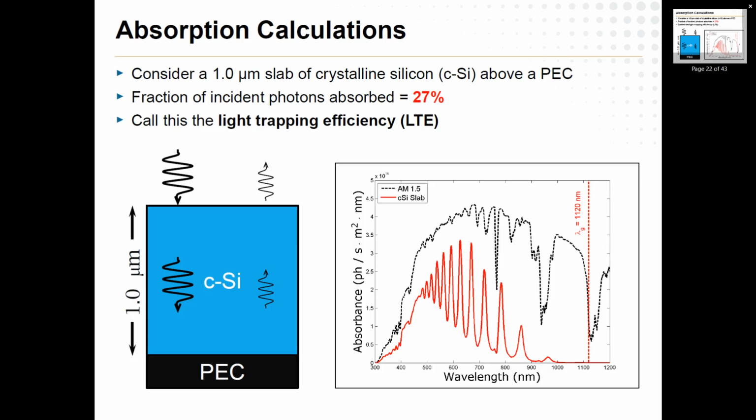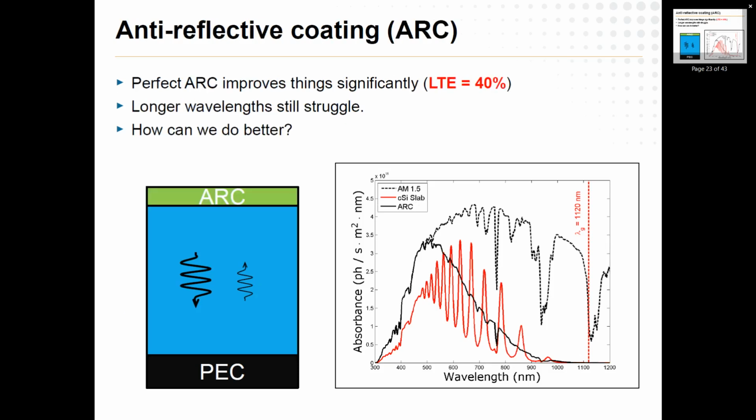So the most immediate thing to say is, well, how can we just make that reflection go away? That's what's called an anti-reflective coating. You just add a little thin layer of silicon nitride, and if you ever take 3300, is anybody taking 3300, I hope? You probably did the math on an anti-reflective coating. It's basically like a quarter wave transformer, remember that, only in optics.